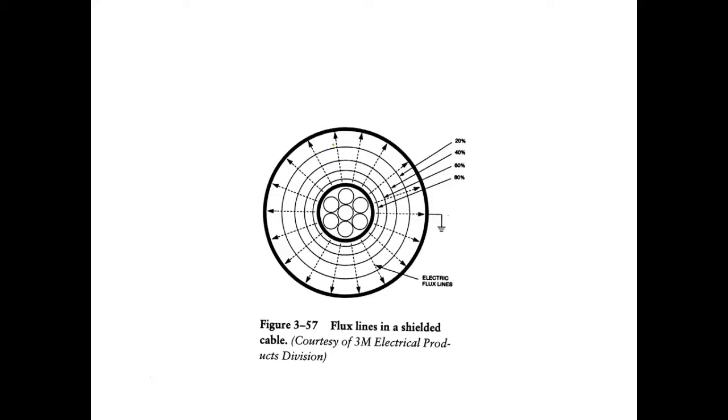because here it says for A. So on this punch down for A, I would use orange, white, orange. I would use brown, white, brown. And then over here for A, I would put blue, white, blue, green, white, green. So, and that's going to route it to the right plugs up here for you, right? You understand? That makes sense?